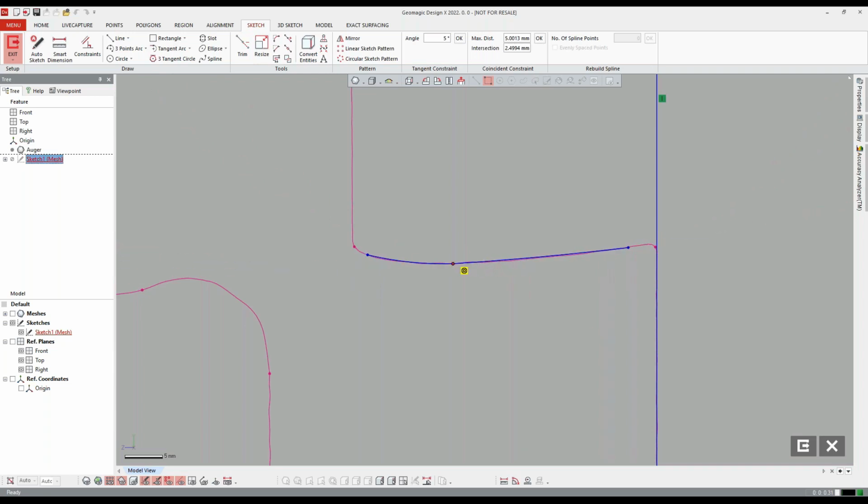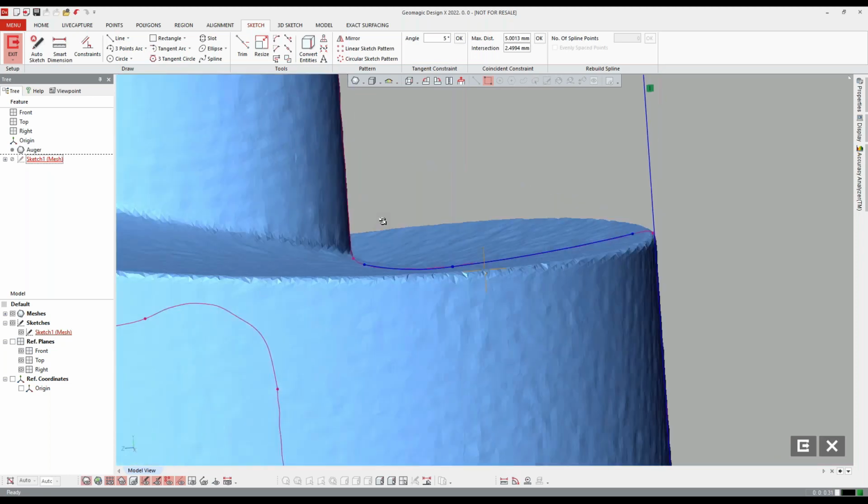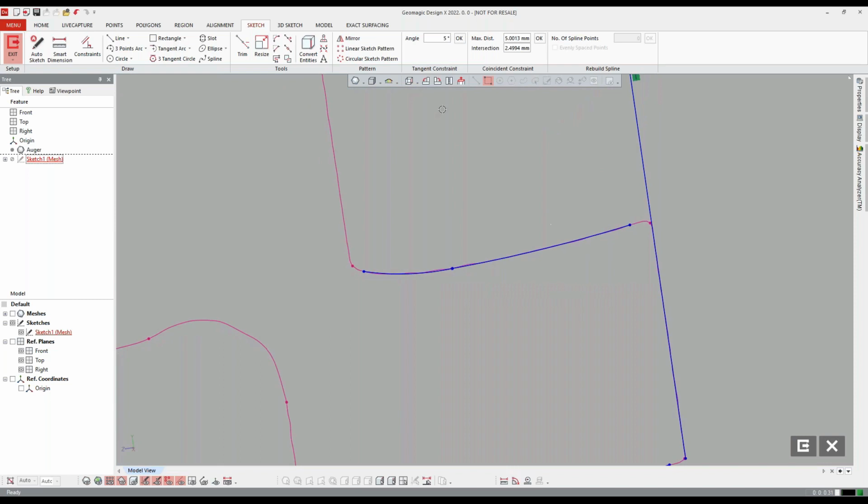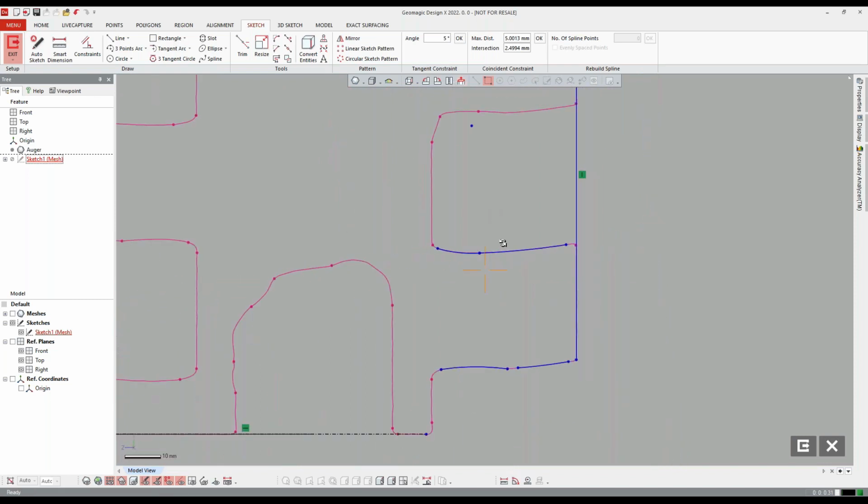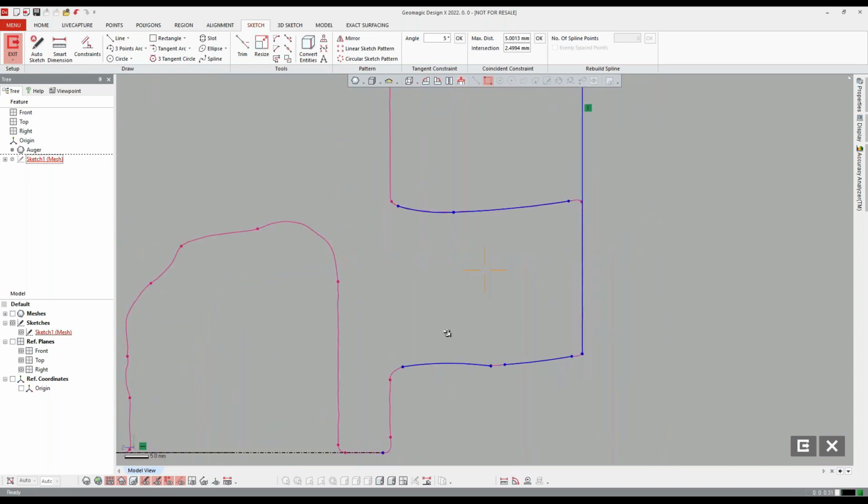No, you drag you there, and we'll fit this. Again, we don't have to be crazy because it is a cast surface. You'll notice I can just drag this around, snap wherever my cursor is. So I can really decide what the arc should look like. If I want to try to make them tangent, I can, but there is a divot in the surface, so I don't think they're really tangent. But, and let's trim these guys here.